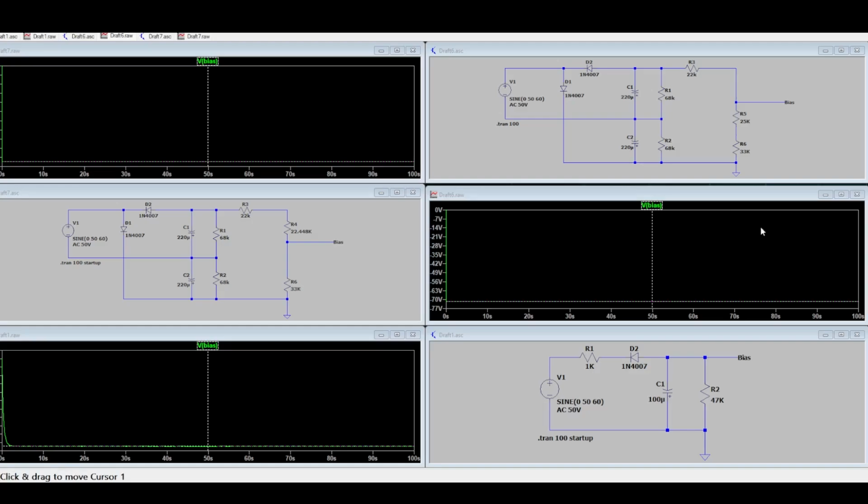We can go all the way up to negative 71. Now, I doubt you would want to go this high, but this does give you flexibility in terms of accommodating for modern tubes that are not constructed to the same level of reliability as tubes from the 1974 Hiwatt era. So this gives us some flexibility to ensure that we're going to run our tubes safely and operate them at a proper bias level. In theory. So this is the theoretical version of these circuits, because this is a simulation. The next step to prove that this is a good circuit would be to build them.